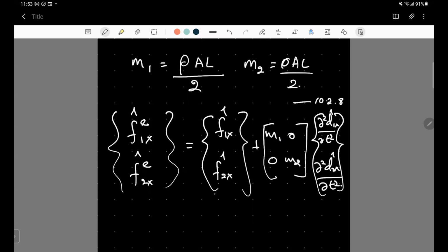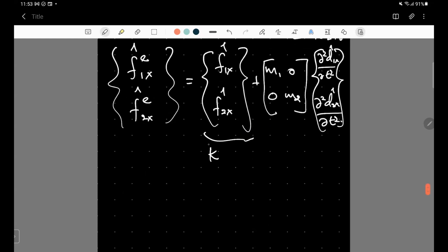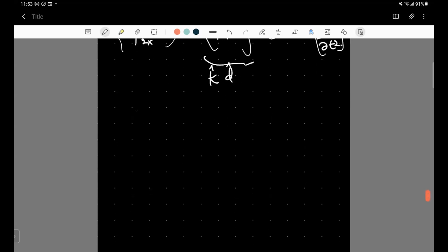So now we can replace this set of equations using the spring constant, K times D representation. We know the internal forces due to static loading. We can write them using the spring constant and the displacement to obtain the elemental equations in the following form.